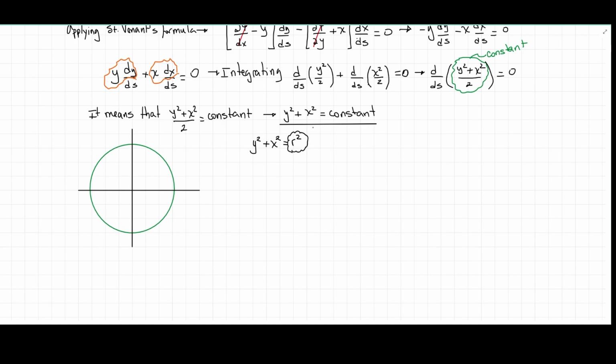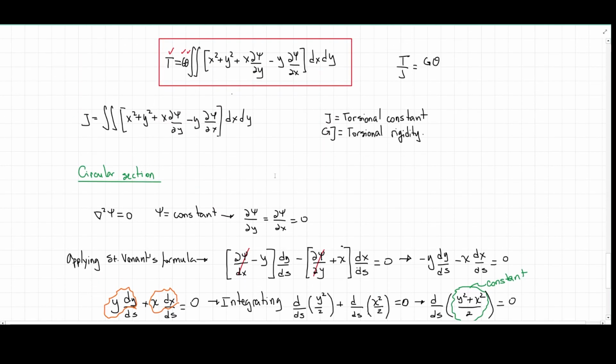And if I go further and say, okay, how do I apply the torsion equation that I found out before, which boils down to finding the torsional constant J for this circular section, how can I do it? What would be the typical procedure to find this J? Because G is known, as it depends on the material, and theta you can also get to know, because that's a type of deformation that you're going to have. But J depends on the geometry of the section, so how to calculate that? Well, let's do this simple example for the circular section.